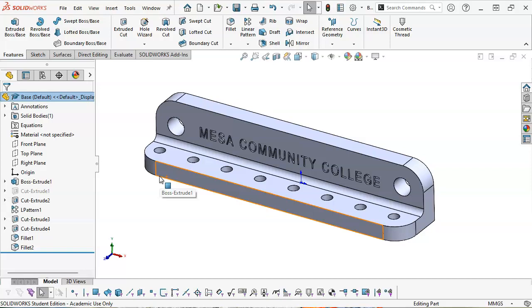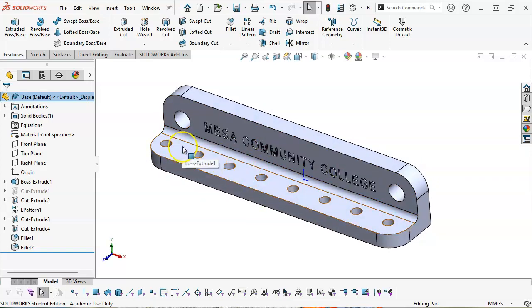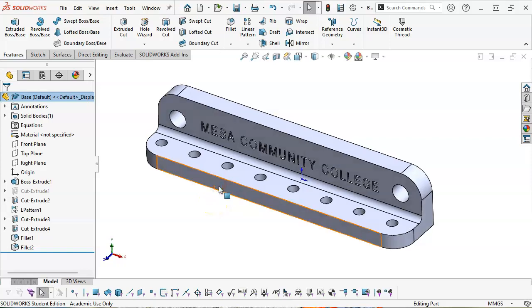All right, so I'm probably going to go hunt down my other single point fonts so I can do this again. And I want to actually run this through some of the CAM programs as an optional. So I do want to show the difference between the single point and the simplex would probably be okay as close as it is, but if it's going to pull up a burr or take longer to machine, then it really hasn't saved me anything. So all right, so we have some other issues to resolve and some dimensions to check, but that looks like we're pretty good on the base.